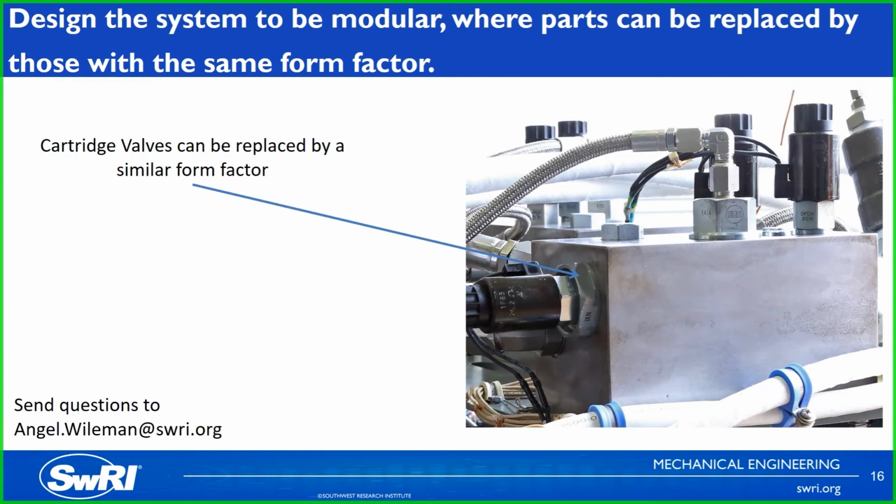So going on that same concept, for this design we used hydraulic cartridge valves, and what ended up happening was that the controls of the generator, its voltage controls, and the controls on a manual flow control device were kind of disagreeing with each other, and so it sent flow oscillations through our system.